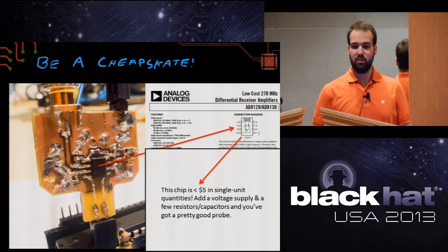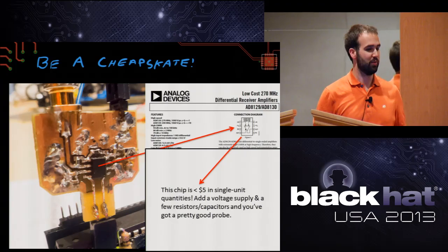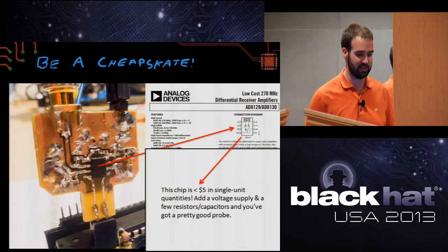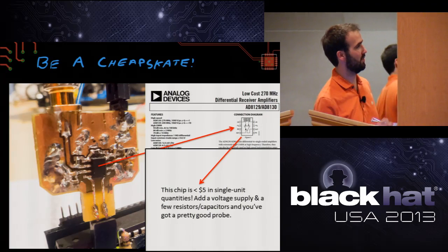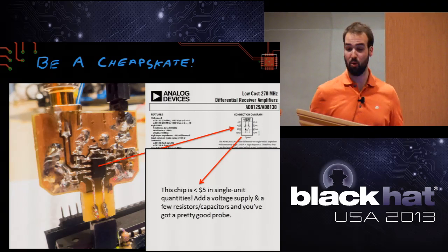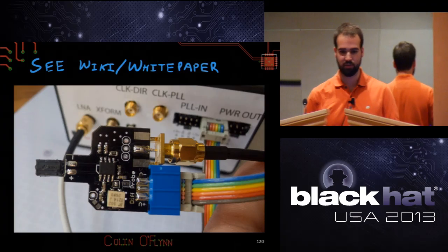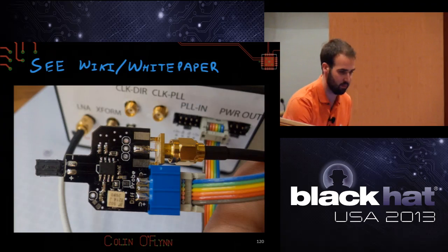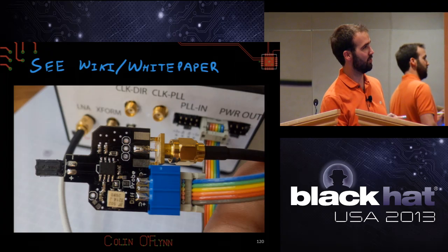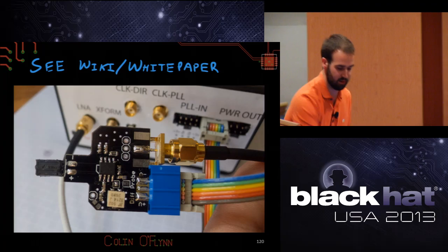But you can build something for what we're doing that works well enough, has pretty good high frequency response for about $5, with a $5 chip plus a few other parts. And this chip will work more than well enough. And there's a nicer version now with PCBs and whatnot. So this shows you the design of the ChipWhisperer in the background. There's this differential probe and you just plug that onto the board.